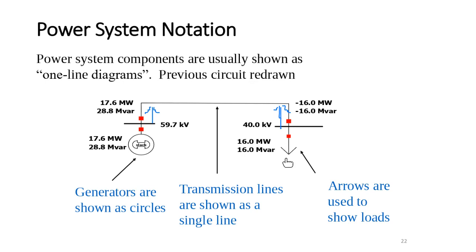When we have an excess of reactive power, for example from an underground cable or a transmission line that has more capacitance than inductance, the power will flow this way. Where will it go? It will be absorbed in the transmission line. But if the transmission line still does not absorb it all, because the capacitance is more than the inductance, it will come to the generator, and the generator has a limit on absorbing reactive power.